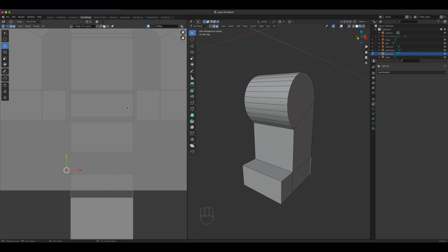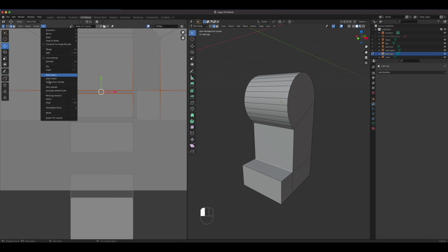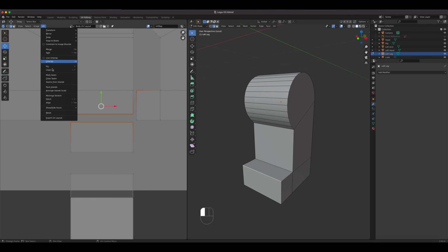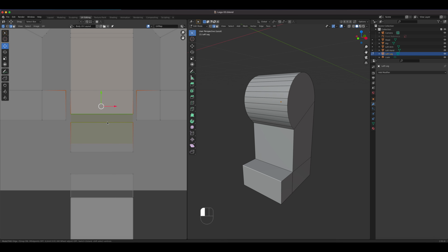So let's do the stitch first. That's quite obvious here, right? So if I click that and then I go to UV stitch, it gives me the preview, press enter, it just goes there, right? And then let me stitch this one, because these two are connecting. UV stitch. You can also do Shift R to repeat the last command.